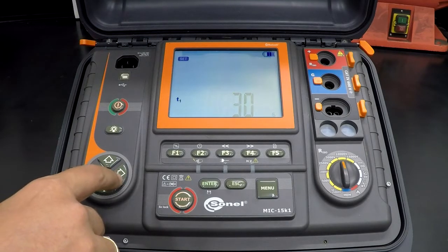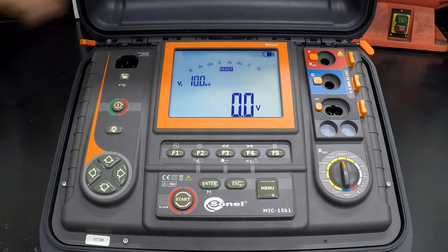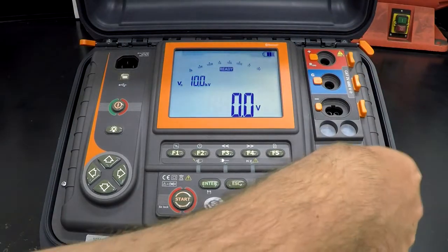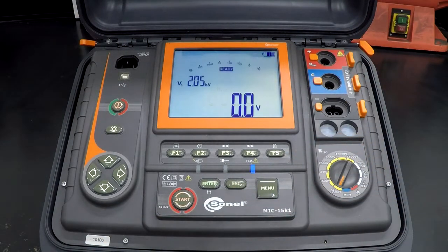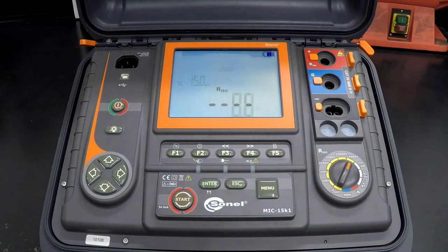Those three measurements help to check the quality of the object isolation. In this meter, security clips have been used, preventing accidentally pulling the test lead out of the socket. A rotary switch allows you to set the test voltage, choosing from 50 V up to 15,000 V. You can choose any voltage, or one of the predefined values from the rotary switch, up to 15 kV using the yellow arrow.